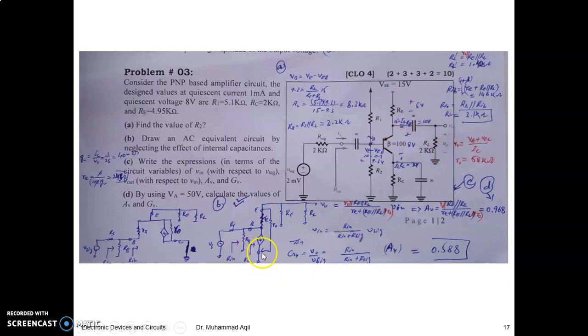So let's draw the T model: collector, base, emitter, internal resistance between emitter and base explicitly at the emitter, current source at the base and collector side, and the current direction is from emitter to collector because of the PNP transistor, right? Then connect the collector to ground, because this would be short circuited. So the collector is grounded, okay?